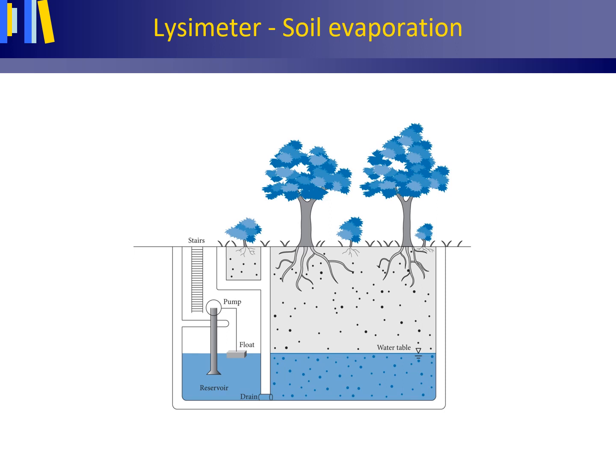The position of the water table in the lysimeter is monitored and can be regulated by pumping measured amounts of water in or out. In a weighing lysimeter, the change in water storage is determined by the difference in mass of the lysimeter. The evaporation is estimated from the water balance.